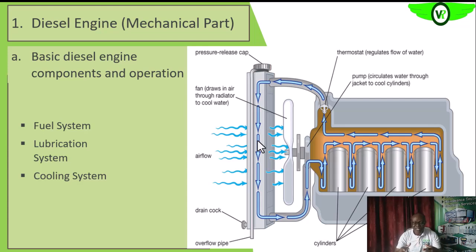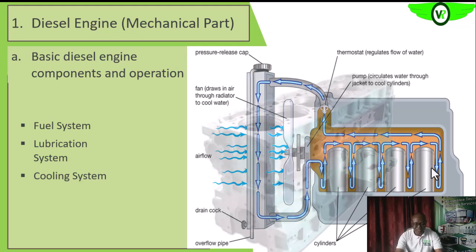That is cooling the hot water that is coming from inside the engine. Okay, so the cooler water will now be sent into the engine itself. So you see that the efficiency of this operation will be affected by the rate of heat exchange around the radiator itself, and the rate at which the pump is sending water, the flow rate, into the cylinders, into the engine. So if those rates are affected, definitely it will affect the efficiency of the cooling system, the efficiency of the engine itself, and may affect the overall output, causing overheating within the engine. So the cooling system is a very important system in the engine itself.